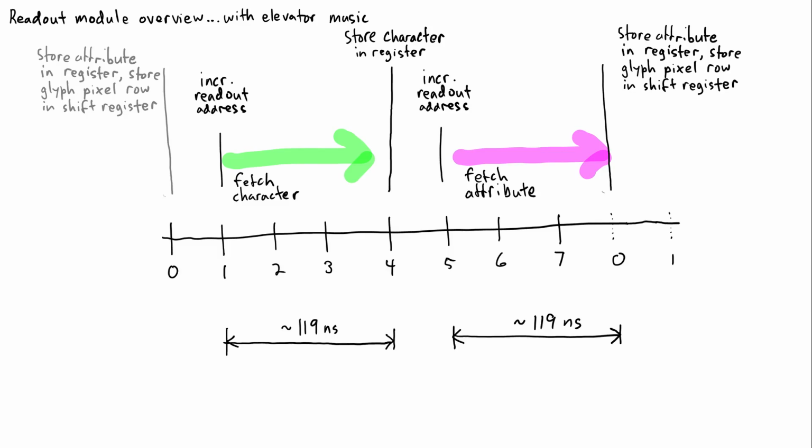Although incrementing a counter is not instantaneous, and we need to meet the setup requirements for the registers in which the data will be saved, so in reality we need the data to appear within 100 nanoseconds or so. The IDT7134 chips I'm using have an access time of 70 nanoseconds, which should meet this requirement comfortably.